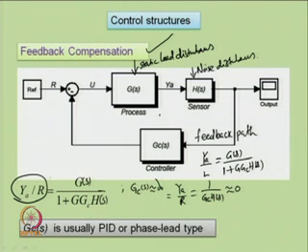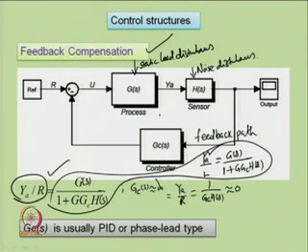If you look carefully, the transfer function with respect to the reference input and the transfer function with respect to the static load disturbance input are the same, thus facilitating one to design a controller conveniently, because the two closed loop transfer functions are equal. So, the same technique or same criteria may be used to design the controller G C S, whereas for series compensation scheme that is not the case.